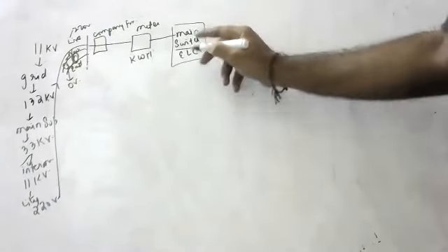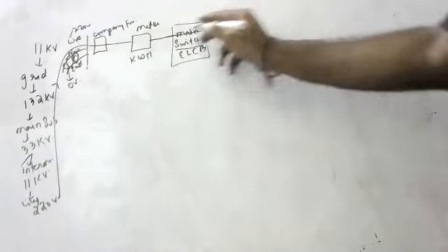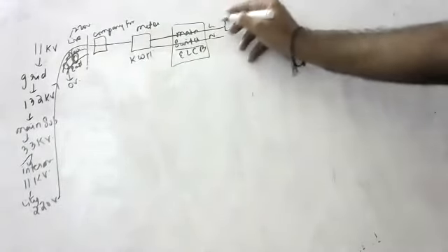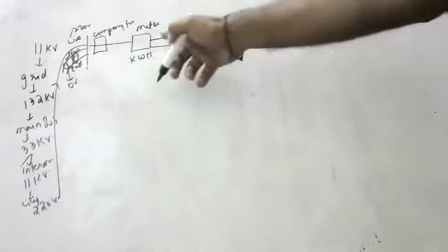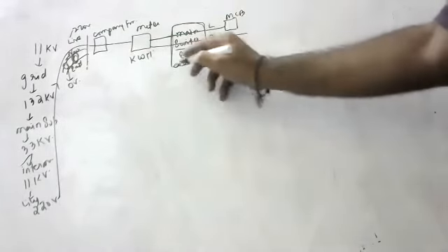Okay, children? Then the ELCB or main switch is connected to both live wire and neutral wire. The live wire will go through it, and the neutral wire also will go through that only. ELCB is connected to live wire and neutral wire, whereas MCB is connected to only the live wire. Children, the neutral wire won't touch the MCB. MCB is a secondary switch. I hope you are able to understand, children. Also, ELCB has an iron coating, and that's why it is also earthed.